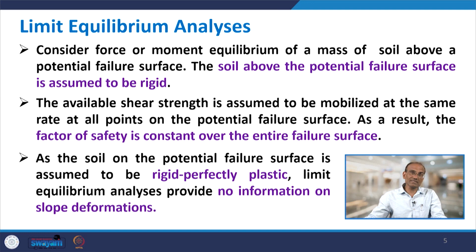In the limit equilibrium analysis, you consider the equilibrium of forces or equilibrium of moments on a mass of soil which is above a potential failure surface. This potential failure surface in geotechnical engineering is many times called a slip circle or slip surface.